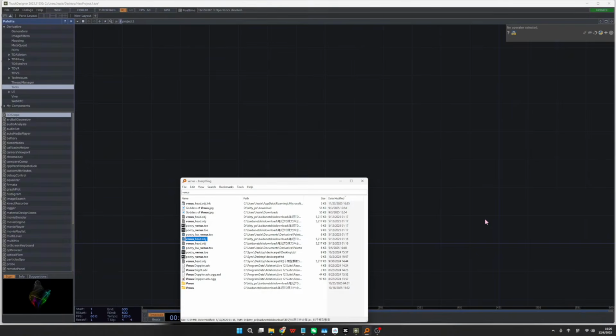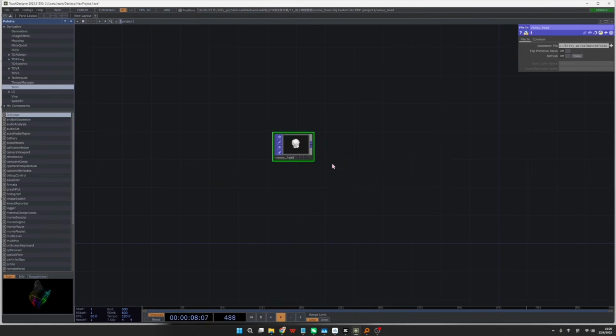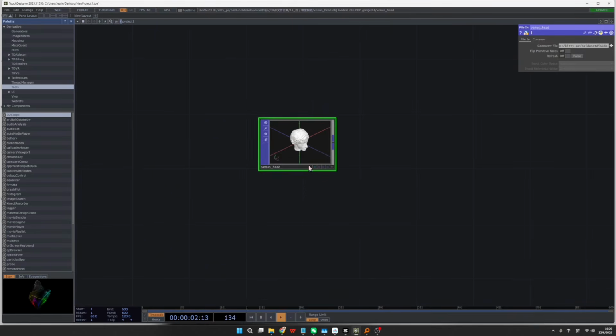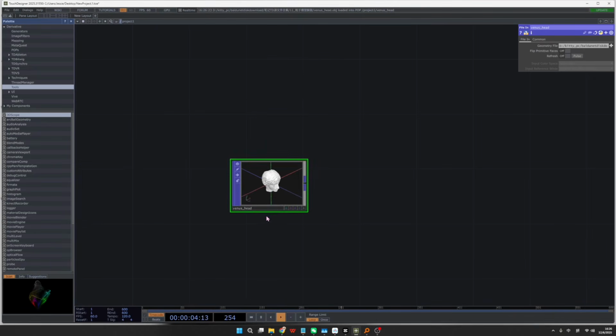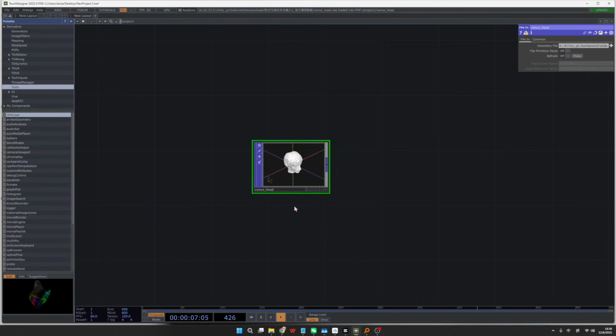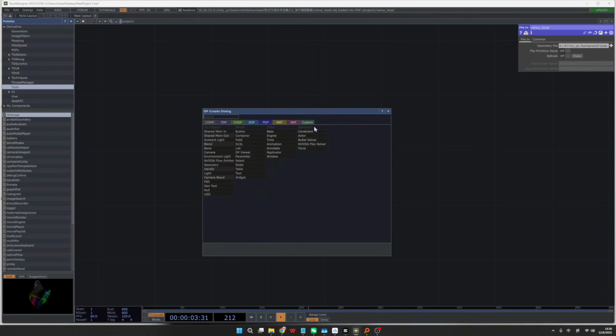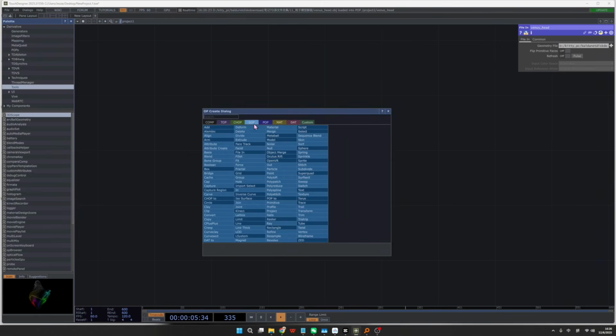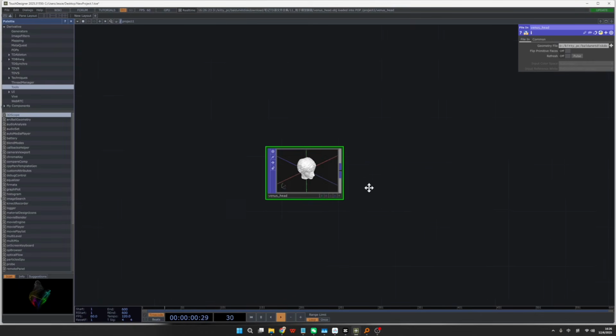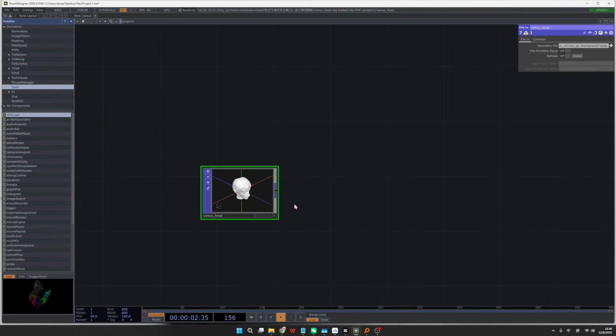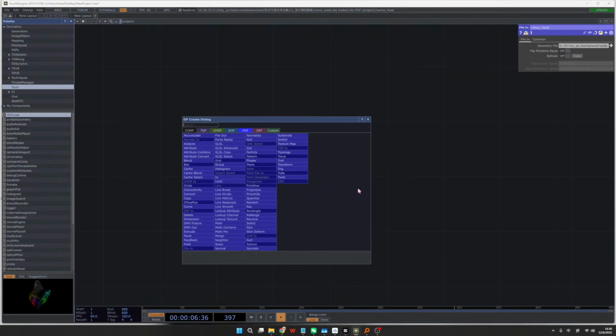Firstly, I'll use this example, Venus head OBJ. If I directly drag the OBJ file in here, it automatically shows as a POP operator instead of a Point File In or SOP operator File In. So far it doesn't change much. To render this out, the basic render workflow is to treat POP as a normal SOP.